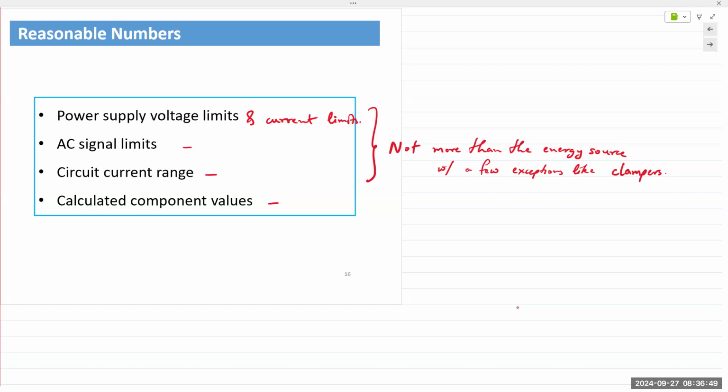So you can either shift it up or you can shift it down. And so a capacitor absorbs the energy in one half cycle, and in the other half cycle that absorbed energy is added on to that AC signal, which behaves like a DC component. So it clamps the output at a certain level and hence is called a clamper circuit. But that's later on in chapter 3.